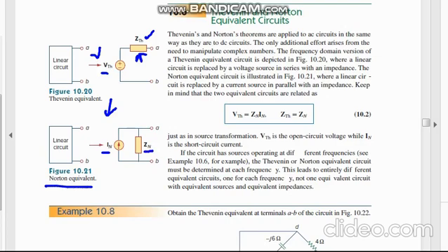Both are quite equal, because Thevenin's theorem and Norton's theorem are pretty similar in fashion while you compute these equivalent circuits. But the basic difference is the source conversion. If you know the Thevenin equivalent circuit, you can easily convert it by source conversion.